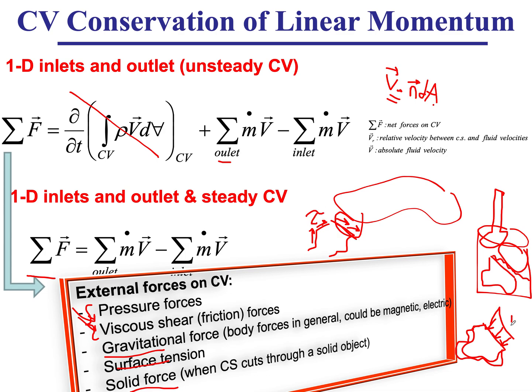This is shear stress, and here we've drawn the pressure. It is the friction that the part that we have cut away and thrown away, which is outside the control volume, it is that effect, that friction, that mass is acting on the mass inside my control volume, or on the boundary of my control volume, whether it's shear, that is shear force, parallel to the area, or normal stress, which is the pressure perpendicular to the area. So that's what these are. So that's when you're cutting through a fluid.